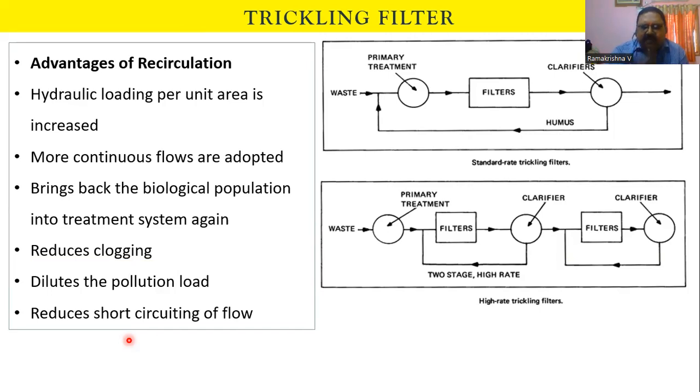So recirculation in the biological system will definitely help in reintroducing active biological solids into the treatment system, so that they will motivate the microorganisms to increase the decomposition of organic solids in the wastewater, right? So this is all about the basics of the trickling filter mechanism.